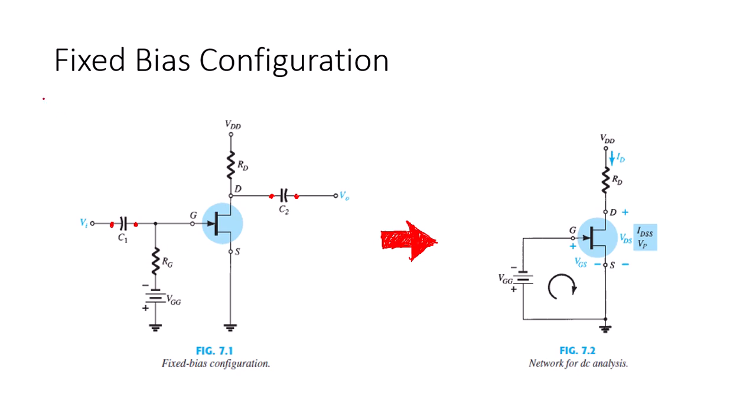Okay? Capacitors in DC analysis will become open circuits, while capacitors in AC will become short circuits.